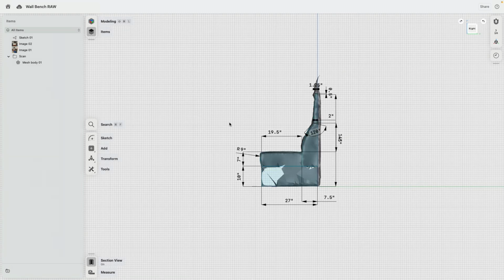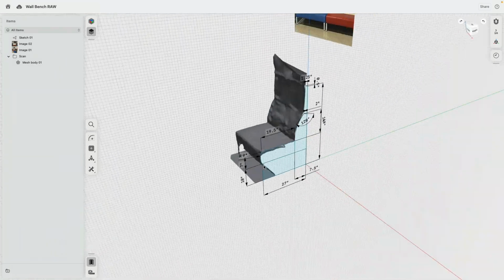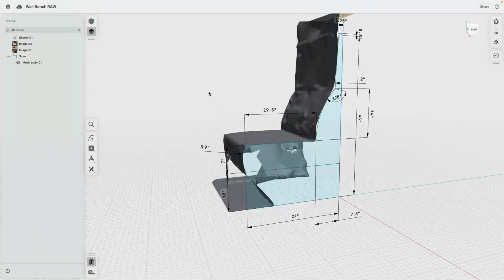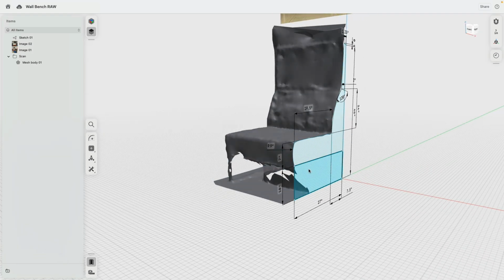I will exit the sketch. You also see that because I had all the dimensions turned on, we can still see actually all the dimensions. We can even go ahead and then later specify everything. So if I go ahead and say 6, you see how outside the sketch, I am still adjusting the sketch. So with all that sketching done, let's go ahead and do some modeling.